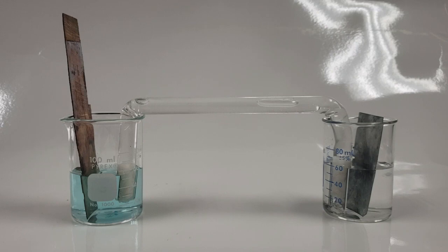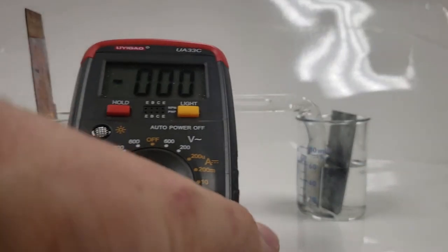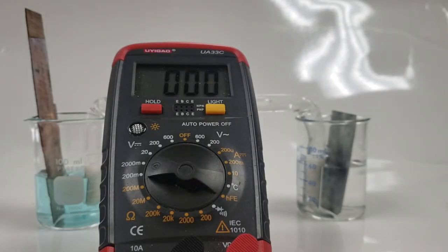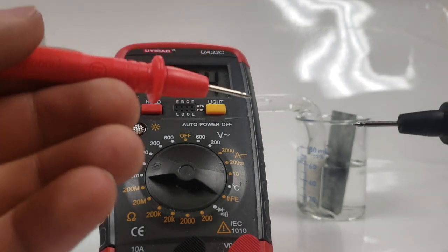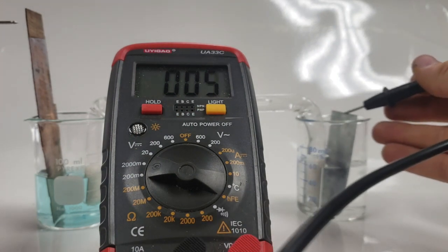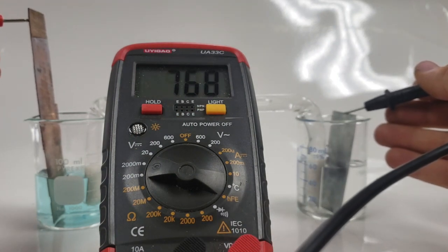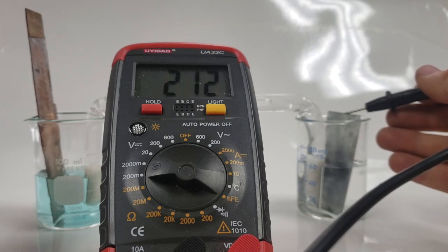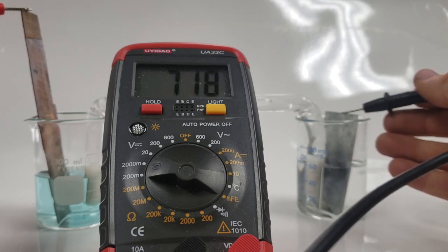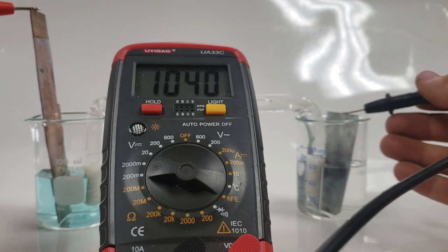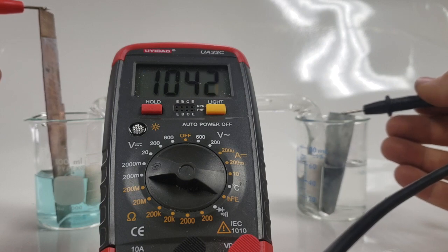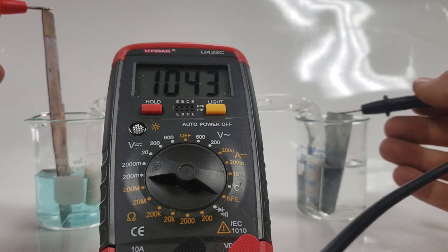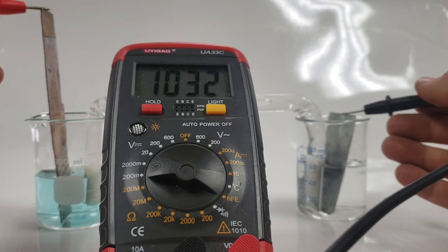Electricity should flow from one side to another, and we can check that using a tool called a multimeter or a voltmeter. And it's not going to be beautiful, but you can see there are numbers there. And if I take these probes here, you can see them, and touch them to the metal, hey, they're numbers. Now, those numbers aren't huge, but there's something. Those numbers are in millivolts. So this is 1,040 millivolts, or 1.04 volts. This reaction should make 1.10 volts, but there we go.